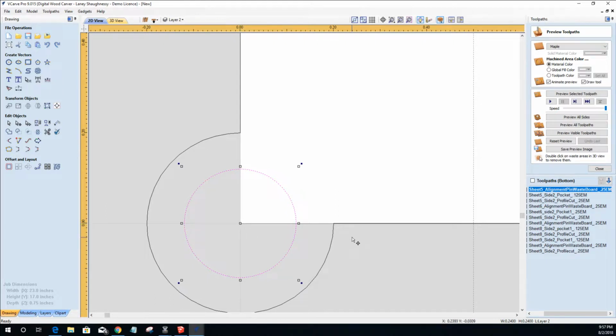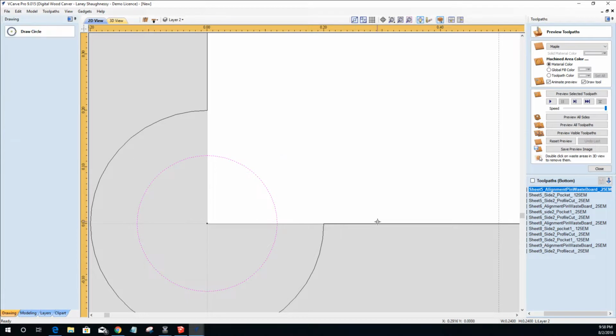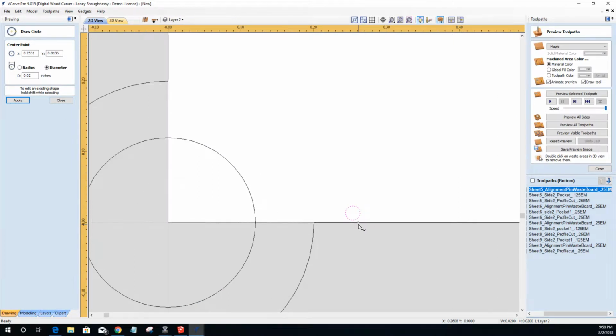If you're like, oh, I can't eyeball the placement, what if my 90-degree V-bit is off or something like that? Well, if you want assurance, you can get a 1/4 inch end mill or an alignment pin or something, and you can touch it up against this fence.